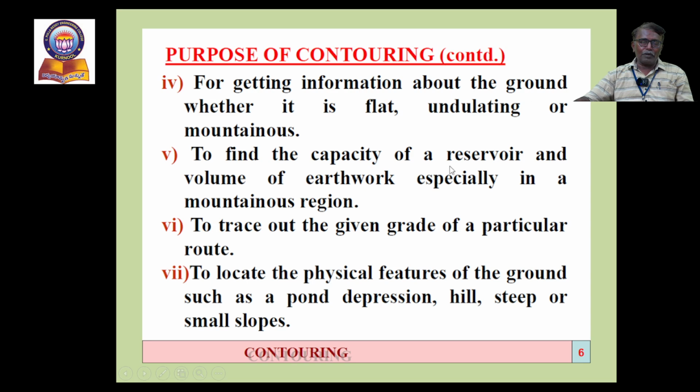To find the capacity of a reservoir and volume of earthwork, especially in the case of mountainous regions. So by studying the contour map, we are able to estimate the capacity of the reservoir, how much water can be stored at what levels. Also, the volume of earthwork can be calculated in the mountainous regions, so for doing any project.